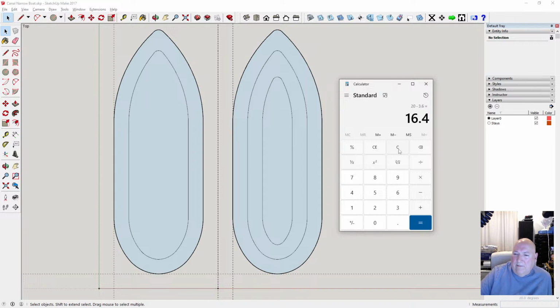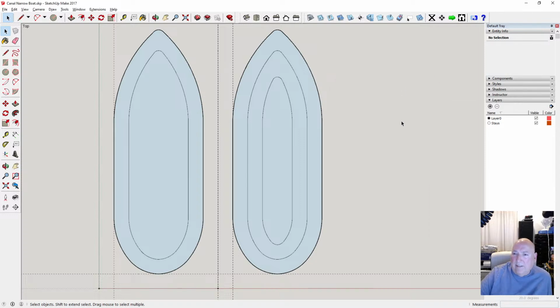Right now, okay, 18%. So what's this pocket tool telling us? So the pocket tool is telling us pocket shift only, zigzag control only, boundary, depth, percentage of the depth. Right, 50% will take you halfway.